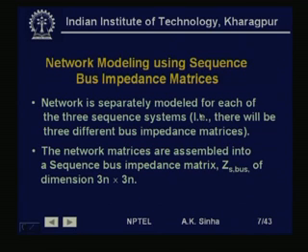Now, for an asymmetrical fault we know that we do the analysis using symmetrical component transformation, that is we get into the positive, negative and 0 sequence voltages and currents, and we had seen for a balanced 3-phase system these 3 networks are independent of each other. When a fault occurs which is an asymmetrical fault, then we find that these 3 networks do get connected by means of the fault impedance at the fault point, and the type of connection depends on the type of fault.